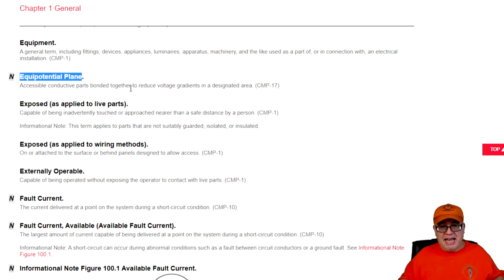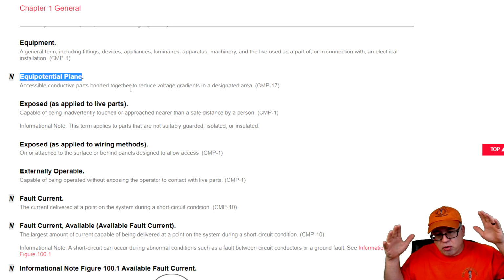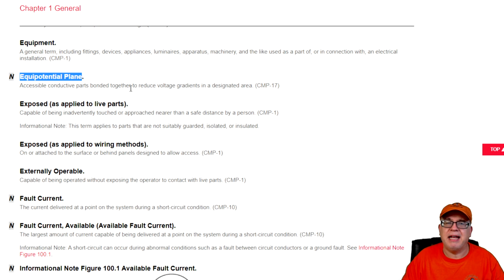So when the cows come up the ramp into the milking house, there could be differences of potential, of gradient potential, and they can feel very sensitive voltage gradients, okay? What we're doing is masking everything as they enter so that we're actually reducing the voltage gradients from what might have been a higher level to a reduced level so that the cows don't feel the difference.